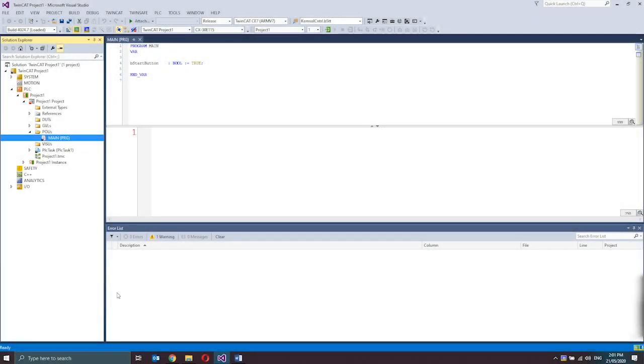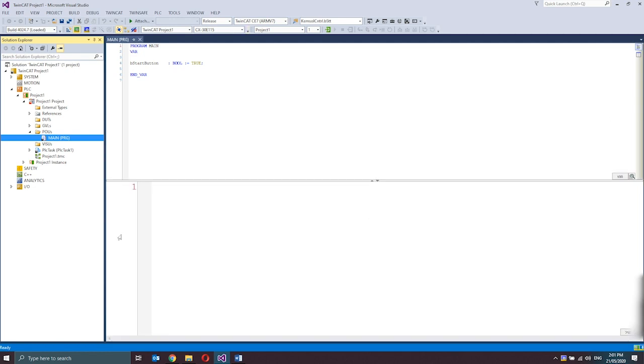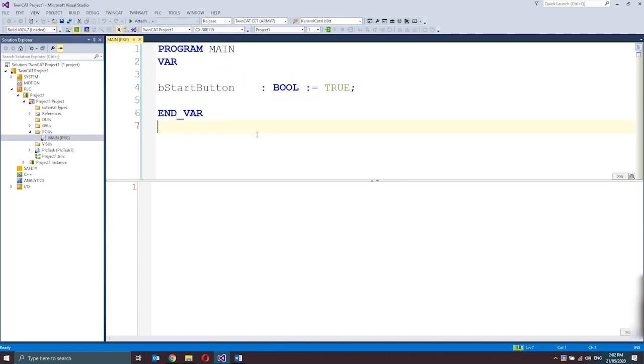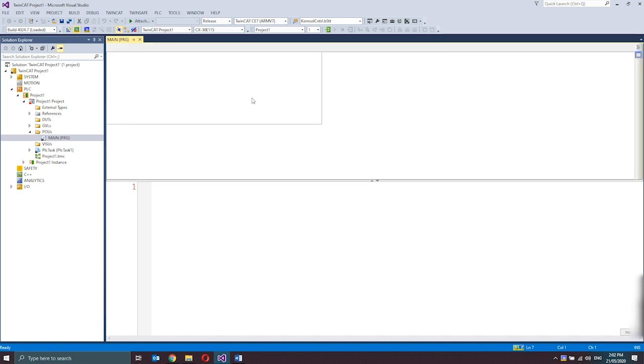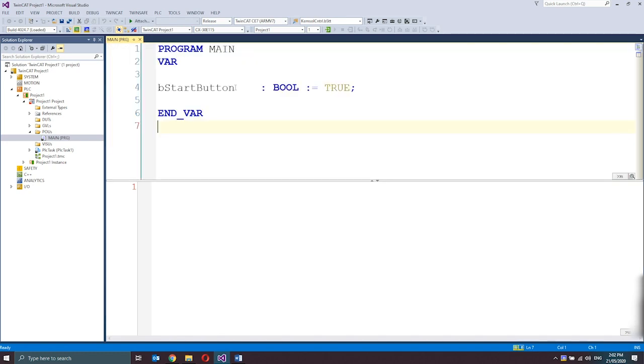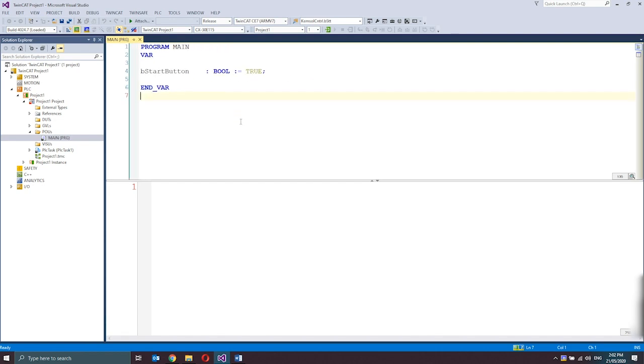Each of those POUs consists of a declaration part and a body. The declaration part, which is the upper window, is used for the variable declarations, either in text-based or tabular form. This is where you declare input variables, internal variables, and output variables, depending on the setting.